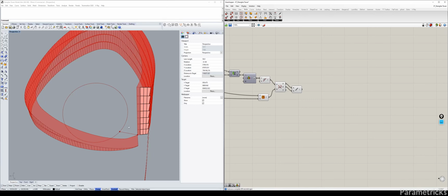Since we only have the bottom one, we only need the top one, like I showed you in the picture. The best way to do it will be to create a plane based on what we have, and use the plane's own vector to create that line. One of the quickest ways to create a plane in our current situation is plane by 3 points, which is under vector and then plane by 3 points.